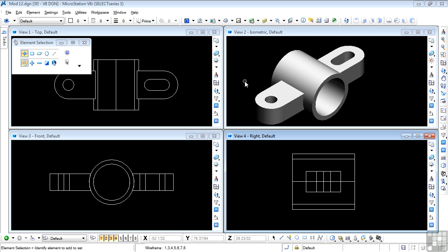3D object. Our next step is to create a 3D sheet model in which to reference saved views of the 4 fitted standard views that we see here. Before you do that, however, you need to think about how you want the referenced save views to display. And in this exercise, we need to display hidden lines in the orthographic references.